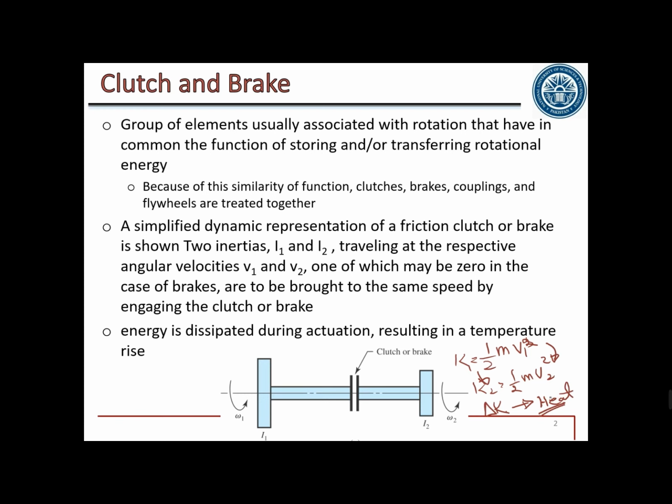In the case of trucks, they have larger mass, so the same change in velocity for a truck causes more loss of energy, so the brakes will be heated more. The lighter the system, for the same velocity difference, the less loss of energy, or less heat will be produced. For larger masses, as in a train, for the same delta V, as the mass is a lot, the loss of energy will be a lot, and the heat generated on the brakes will be more as compared to a car, a bicycle, or a motorcycle.